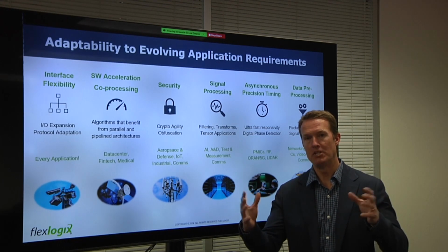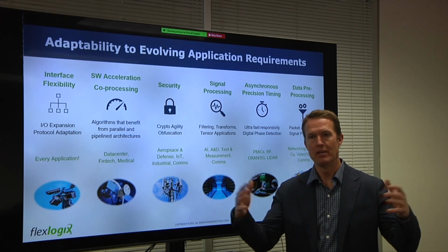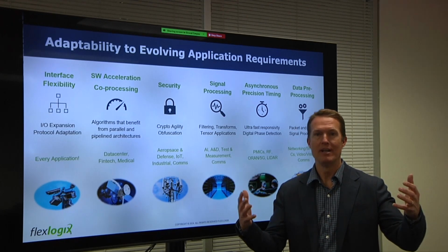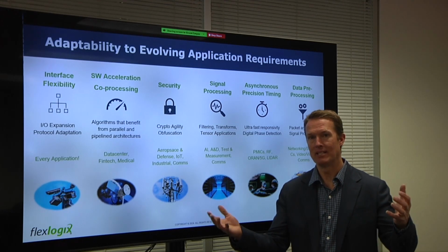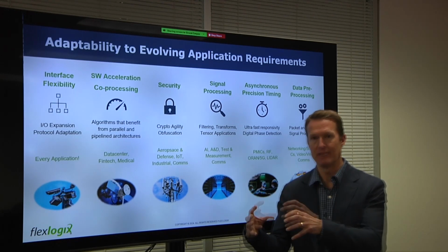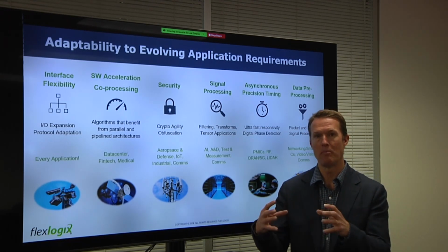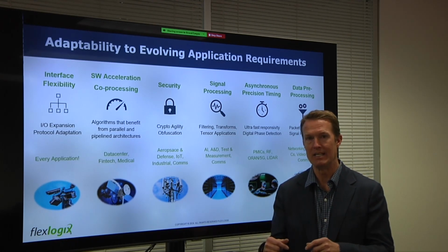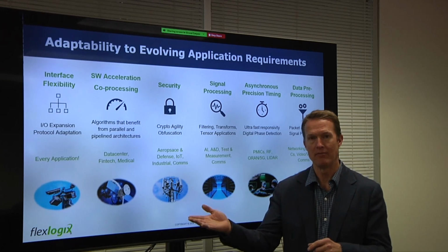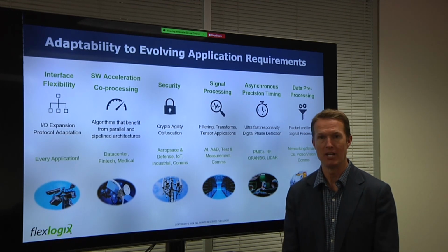The complexity of FPGAs is growing, and they're becoming bigger, require more power, and are more costly to implement in the system. Most applications only require a small piece of this software algorithm to be accelerated. Therefore, integrating a small piece of programmable logic into your IC can provide those eFPGA benefits without the cost and power associated with a discrete FPGA.